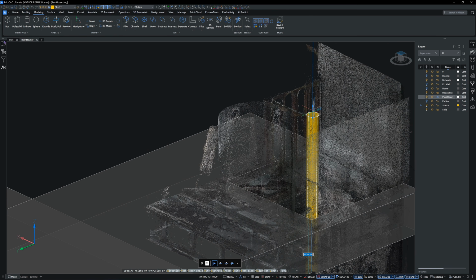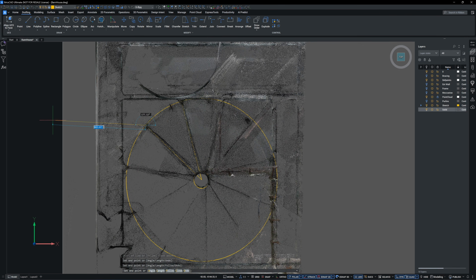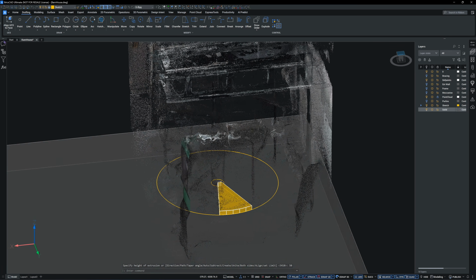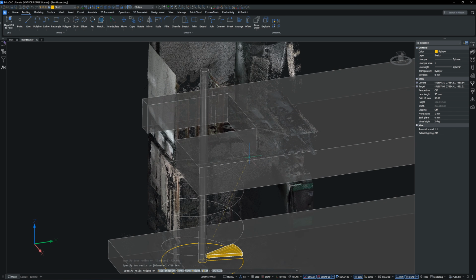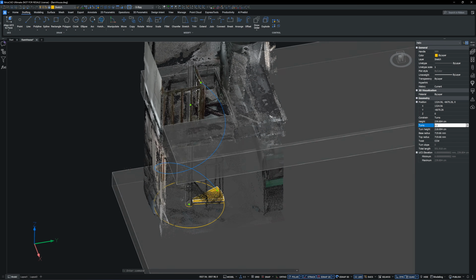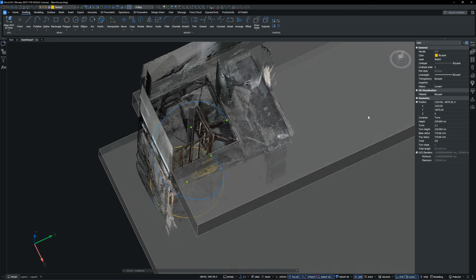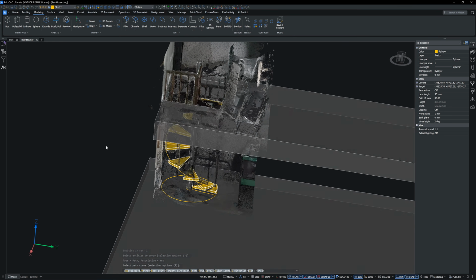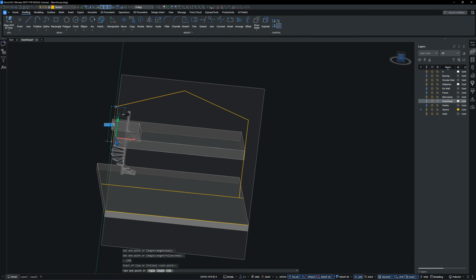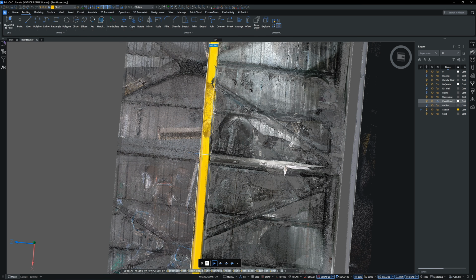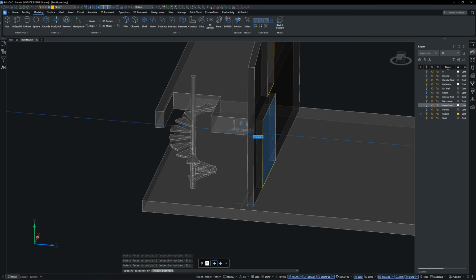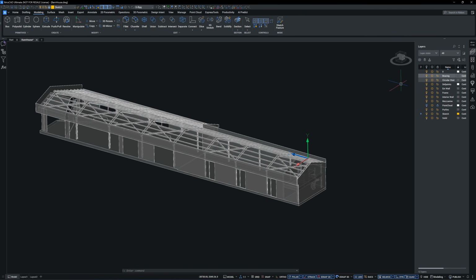And here's how I model the spiral staircase. I start with the central column, then create the first step at the lowest position. To array the staircase step, I will create a helix as the part around the central columns. Then I use the array along path command to generate the staircase step along the helix. And here's the final wall, which I believe is the HVAC room.